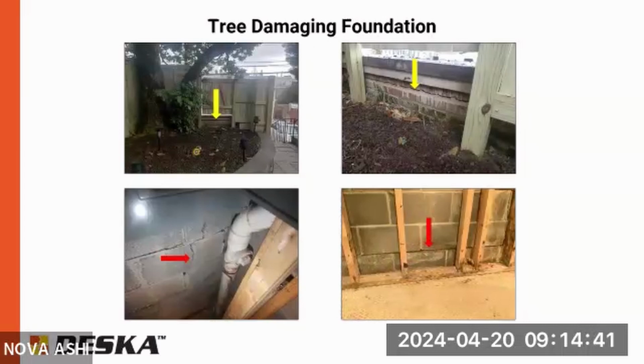Typically, the cracks are first. The next step is the shearing and the blocks sliding on each other. That's typically a little bit more serious, and the repair methods actually change once you have shearing. So if you have shearing, that's definitely a serious issue.